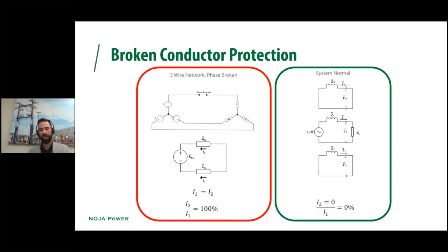It's taking the ratio measurement of the negative phase sequence to the positive phase sequence and using that as the protection operation rather than the absolute magnitude of each of those individual negative phase sequence components. Okay, so by looking at the comparison between I2 and I1, you can then infer what sort of fault is ongoing on your network to be able to get some real clarity about how that system is behaving.